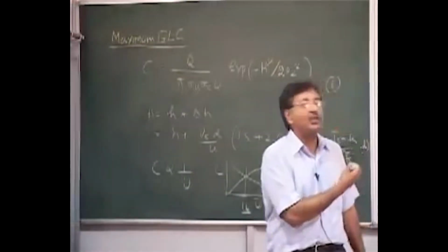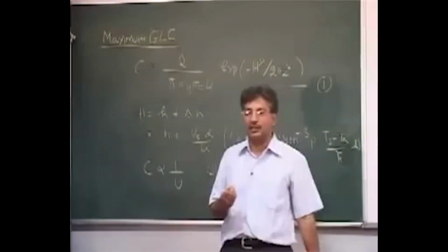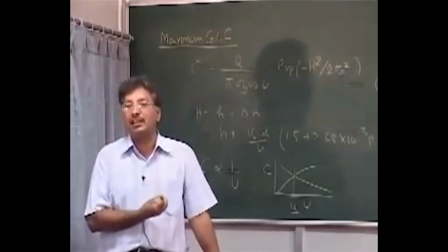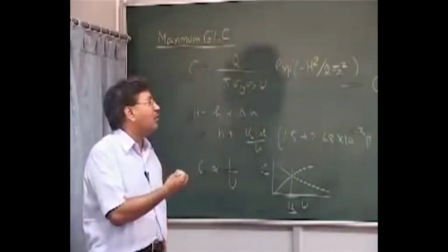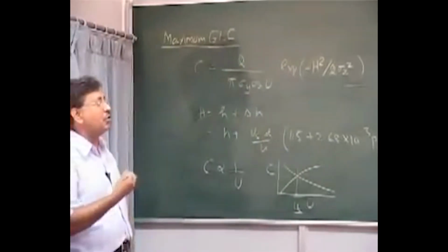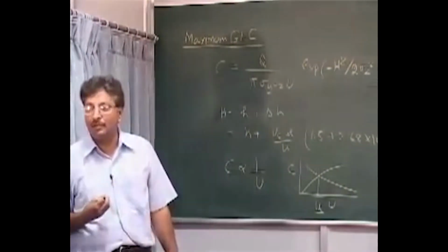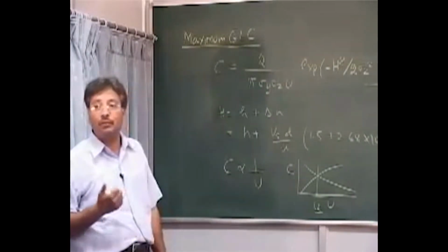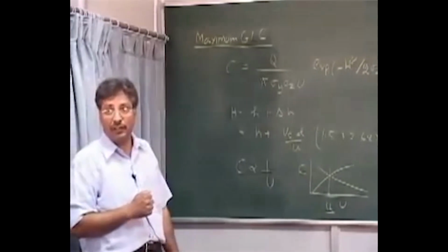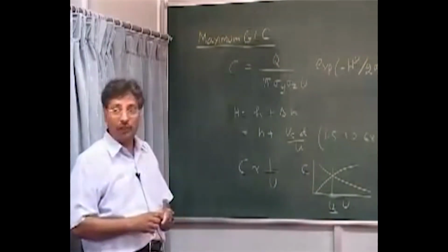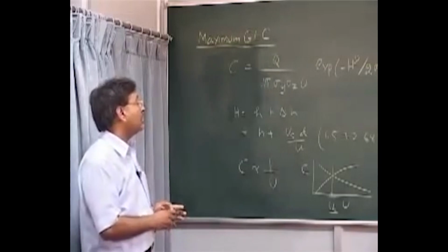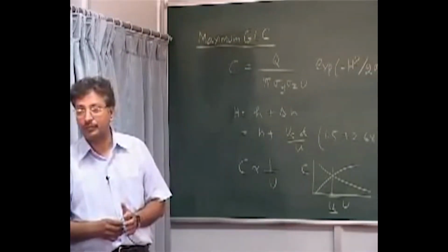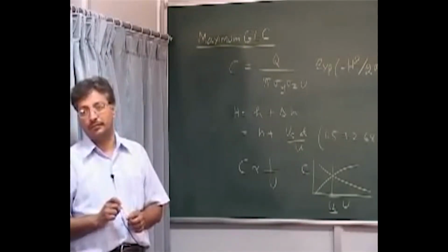You see, the calculations are simple, but you have to apply those things and get an answer which will help you make the right decision. This is all we are doing for decision making: how much pollution is to be controlled, whether the plant can come up or not, where it can come, or whether its maximum impact can be in the vicinity of the people where they live. This kind of situation we do, and in this way you can even find out the worst ever possible maximum ground level concentration. Do you have any question?